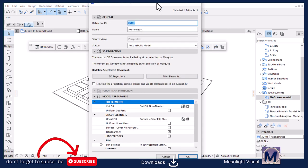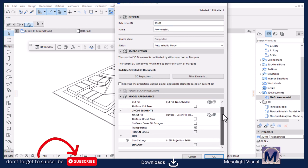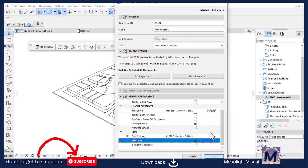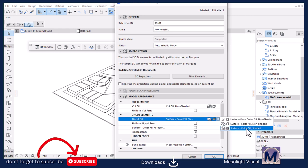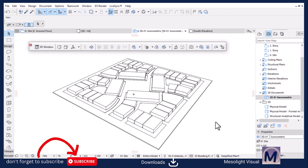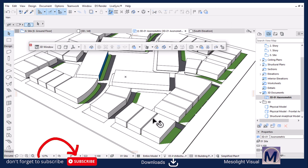So what I want here is to activate the shadows. If you go down there below, you then activate shadows, and then I think everything is fine. Uncut fills are shaded, which is fine, and then hit OK. There we go. We have now our shadows in place, as you can see.